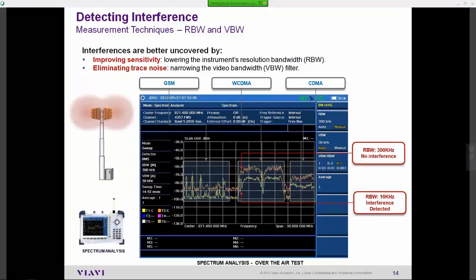Meanwhile, because these GSM channels were adjacent to LTE and UMTS, this strong transmit power on the uplink was interfering and preventing the other technologies from reaching their optimal performance.